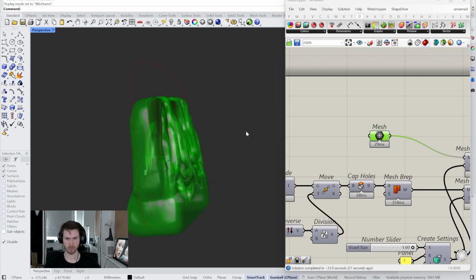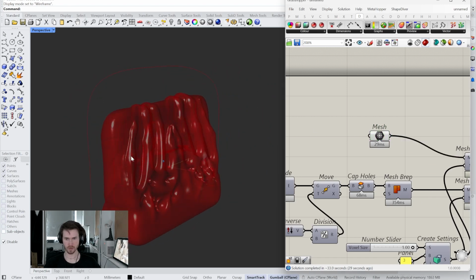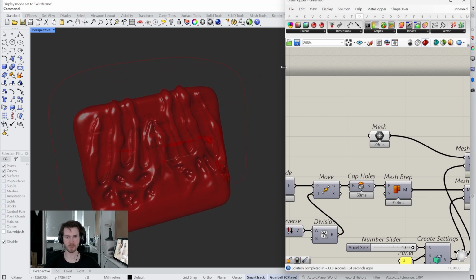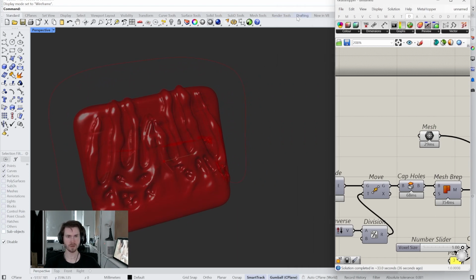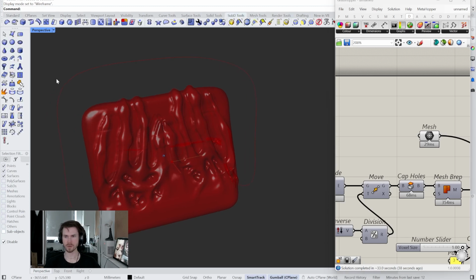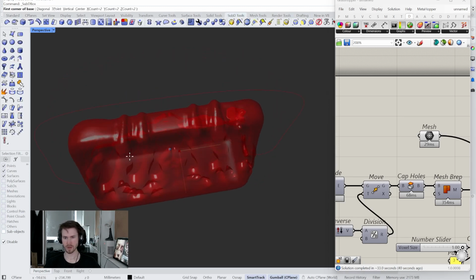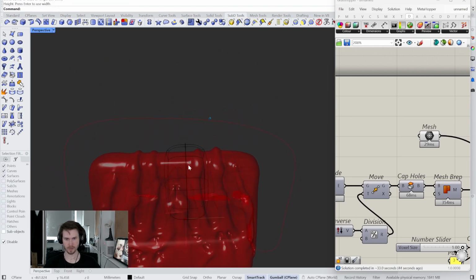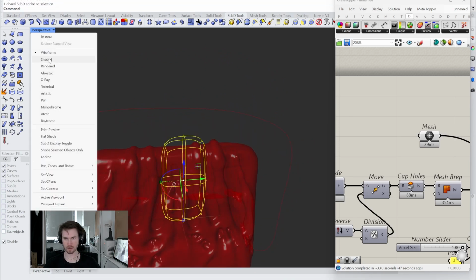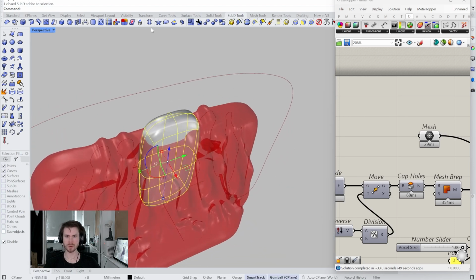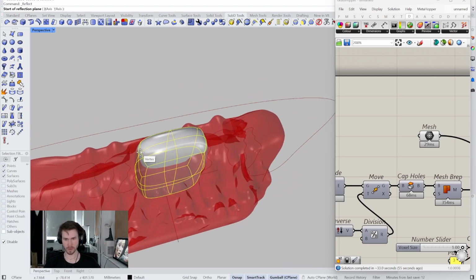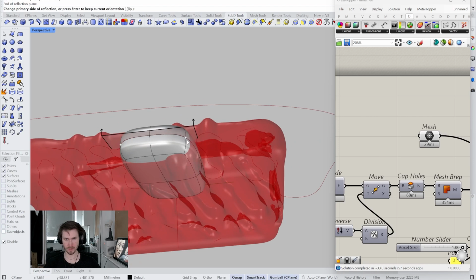It's a pretty normal rectangular prism, like a box. We could probably just model it with some sub D tools and approximate it really quickly. So let's do that. Let's go to sub D, start with a box. We'll draw this box. And let's go to shaded view, and we'll just turn on the symmetrical, the reflect for sub D objects. Turn on OSnap,